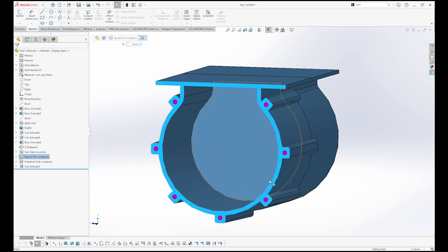And so I would say that in this perimeter we're about, I don't know, 90, 95% of the same and/or uniform wall thickness, with maybe another 5% where these ribs are. But in this particular instance, the wall thickness is 10 thousandths of an inch.